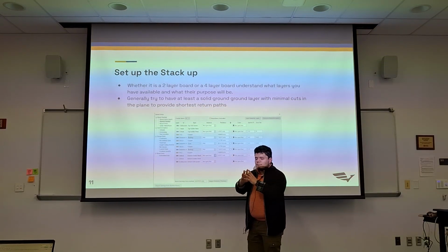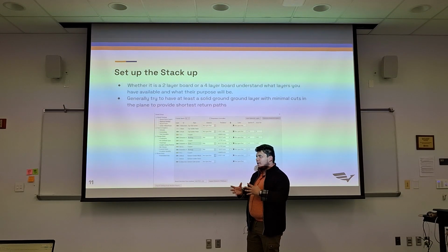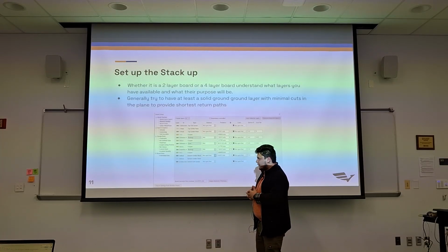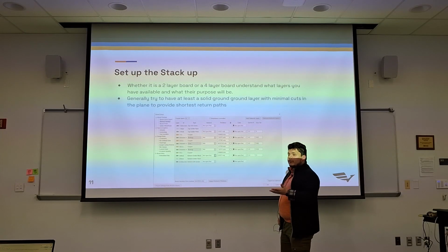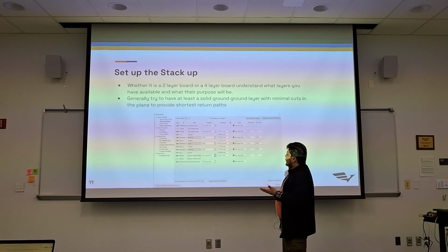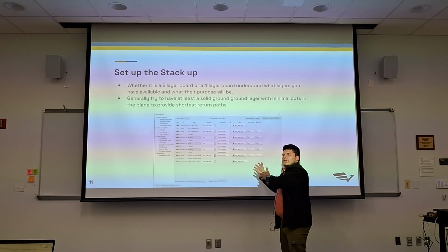And so this is KiCad specific, but if we were to put this in any other modern EDA, EDA would be your design software, electronic design software. Sometimes they have field solvers, and so you'll actually be able to get your impedance control calculations in the software.